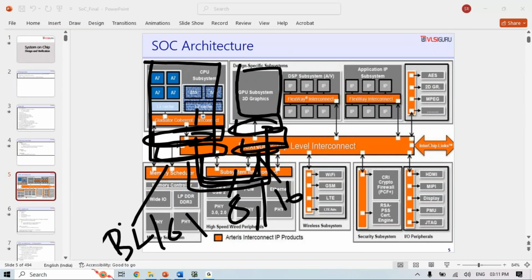In this whole picture, what is the role of UCIe? It identifies whatever protocol the protocol layer is supporting: is it CXL, is it 2.0 CXL or 3.0 CXL, is it PCI Express, and if it is PCI Express, is it Gen 5 or before Gen 5, or Gen 6? Or it identifies that it's neither CXL nor PCI Express, which means I have to process raw format data. So it identifies everything, converts everything into Flit format and sends it.